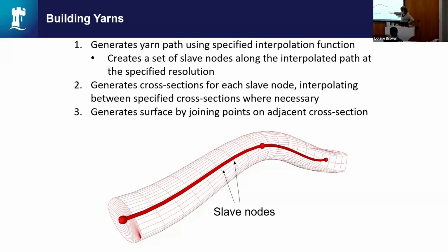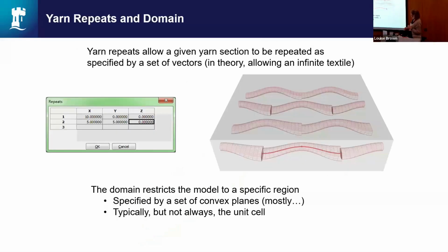So essentially, you can see this one starts off with a circular cross section and ends up with something that's a rounded-off square, and it interpolates between the two and gradually changes. So you can have different cross sections. And so typically what you do is you specify the minimum repeat that you've got. If you've got something like a normal shirt, the plain woven thing, you just do literally one repeat like this. And then what we do is specify repeat vectors. So X, Y.